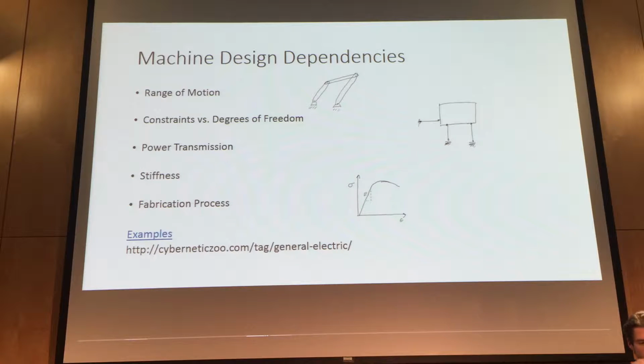It also causes a lot of issues in the assembly process, because you're trying to push 2 pieces together, but it turns out that you have 2 locating features that are fighting each other, so you have to wiggle them around, and you end up mashing something into place, and so you get inconsistent assembly steps.